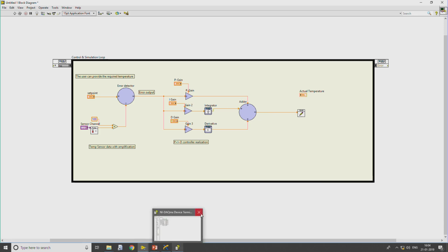right. And moreover, if you recall the driver circuit, in order not to draw more current and not to damage the circuit, we can restrict the input voltage connected to the driver to not more than 1 volt.